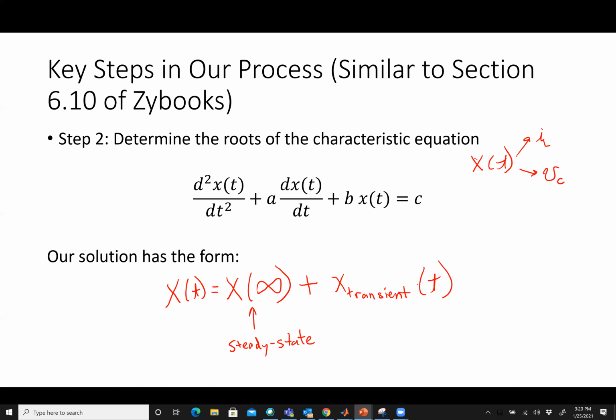Now, what is always true of a transient solution of any differential equation? You're going over this in 2254, or you will be very soon. But you've taken differential equations to get to this class. What should be true about that transient solution? Always. It happens after the switch closes, yeah. It eventually becomes zero. Eventually becomes zero. Yeah, that's right. Unless I had no loss in the system, in which case it doesn't, but normally it's going to go to zero. What kind of math function is it? Logarithmic, I think. No, exponential. It's always going to be exponential, okay? That's closely related to the log, but it's always going to be an exponential.